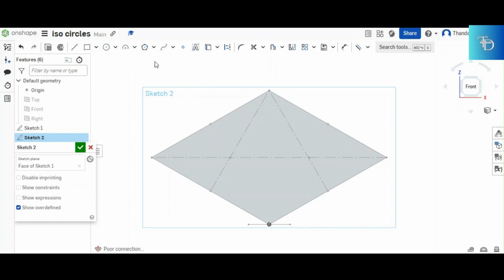Alright, so the next thing that you do, you take your compass, you place it at that center, that station point there. You open it up to there. Automatically it's gonna go over. If everything was done accurately, when you place your compass there, it should go over and touch the second point right there. And then if it touches, you carry on and construct your curve.